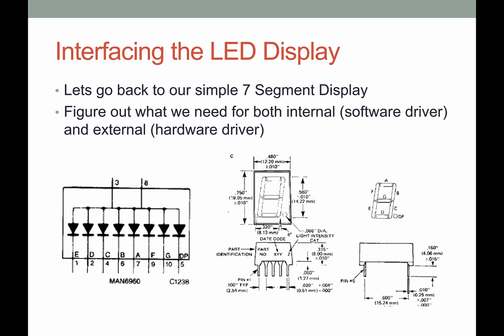But remember, our goal first is we're trying to hook up this 7-segment display. So I think I've gone over that in enough detail. And so what we're trying to do is we're trying to go from this, and we can set it up as having something like VCC here, and then having each one of our output pins, we have an array that has resistors tied to it.